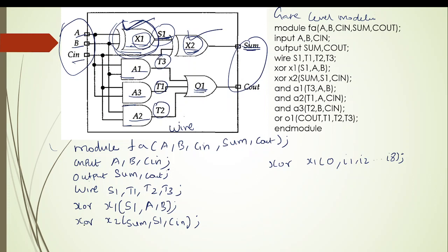So the first line XOR and second line XOR can be anywhere. So this can be written here also. The second statement can be written first. So it will treat both statements as executing at the same time. So this thing you need to understand while writing the program in Verilog. So next,